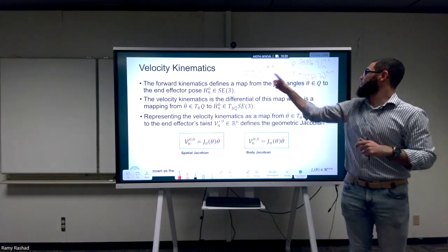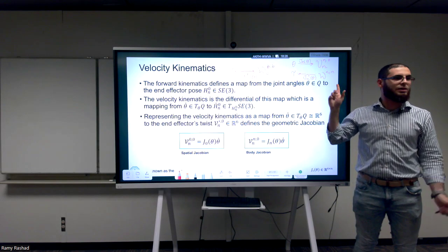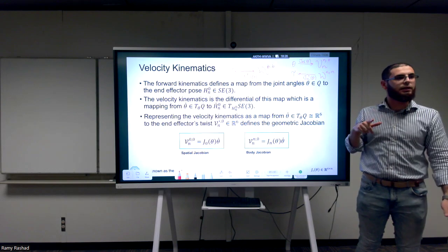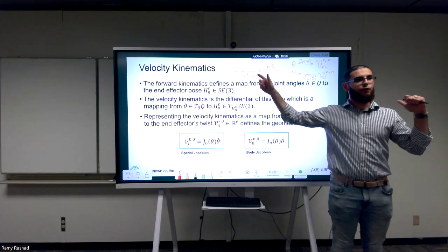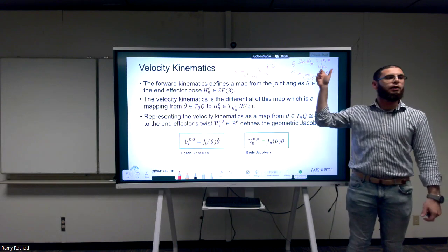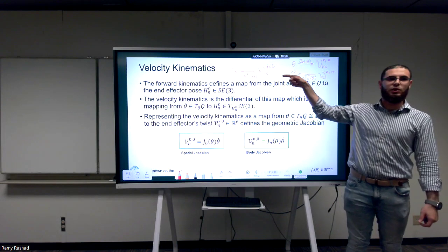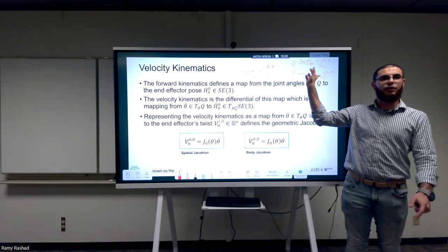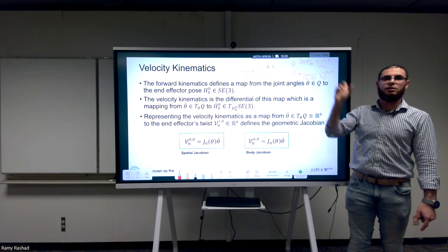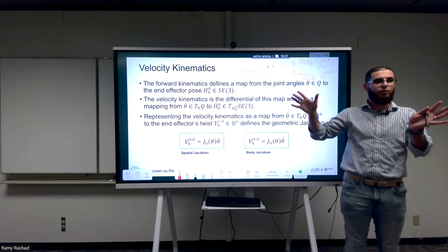What is the relation between M and the J_n here? Just from the picture. The inverse, exactly. So the M matrix that we talked about before is nothing else than the inverse transpose of the Jacobian. The Jacobian transpose goes in this direction, and the thing that goes from the individual thrusts or the individual torques to the wrench would be the inverse transpose. This is just an overview, and this is everything you need to know about kinematics.